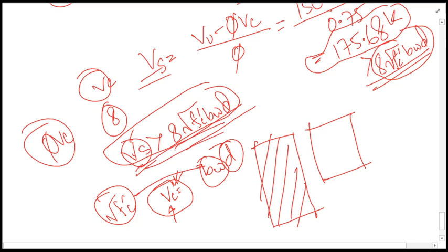And in most of the cases, you might be watching that minimum reinforcement is required, or no reinforcement might be required at all, or even if it is required, that will not go beyond even 4 root fc prime bwd, I hope. And that's how you'll have to design. But in case it is exceeding this, then you must change the concrete properties, the strength of the concrete, or the dimension of the concrete you must increase so that it can resist the shear force. So that's how you have to provide the shear reinforcement.